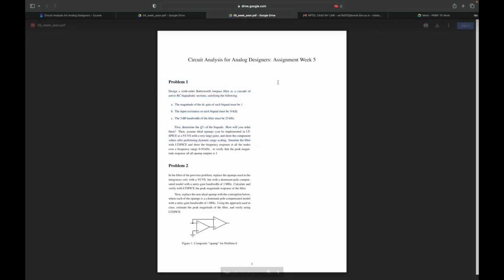Yes, sir. In week four, I committed a mistake, sir. That DC gain, I got an inversion, sir. If I follow your recorded lecture, you interchange that inverting terminal. While changing that inverting terminal towards the output side, that DC gain sign will change, no, sir? Yeah, correct. So that's what I showed, right? You can put that inverter before or after. Based on that, the DC gain at the output will change.